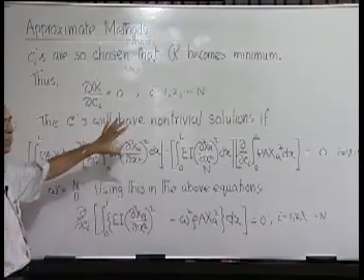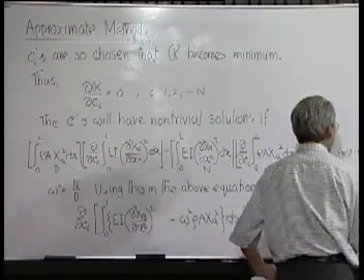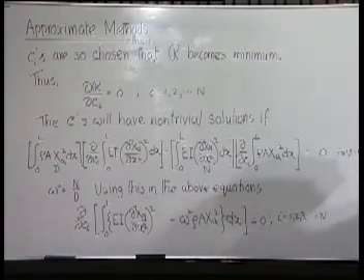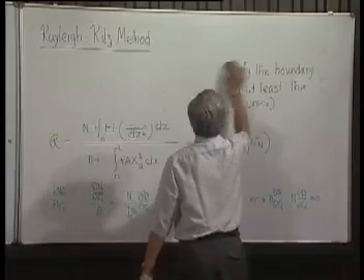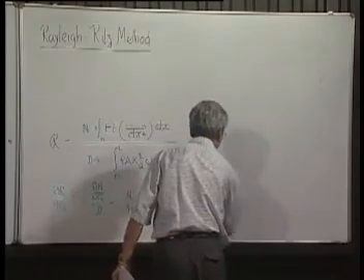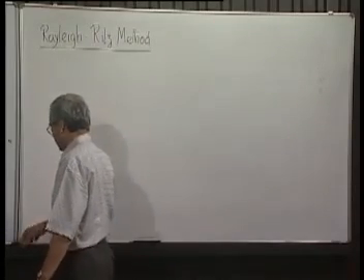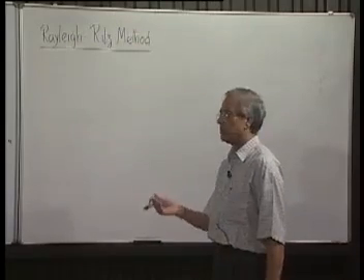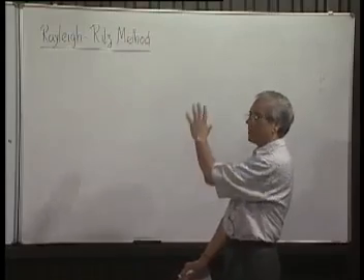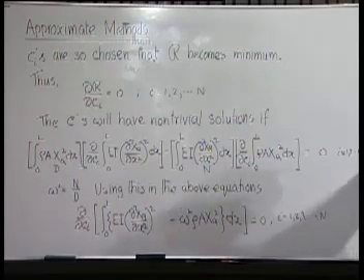We will try to explain the whole process with the help of a specific example. Let us take the same case of a tapered beam. We have found out the fundamental frequency by Rayleigh's method, with Grammel's modification. We also know the exact value. So it will be easier for us to assess our answer which we get from this, at least the first mode. Because we have to keep our analysis and board work less, and also the objective is to demonstrate the use of the principle to find out higher modes, we will take only a case where we will find out up to the second mode. So the example is the same.